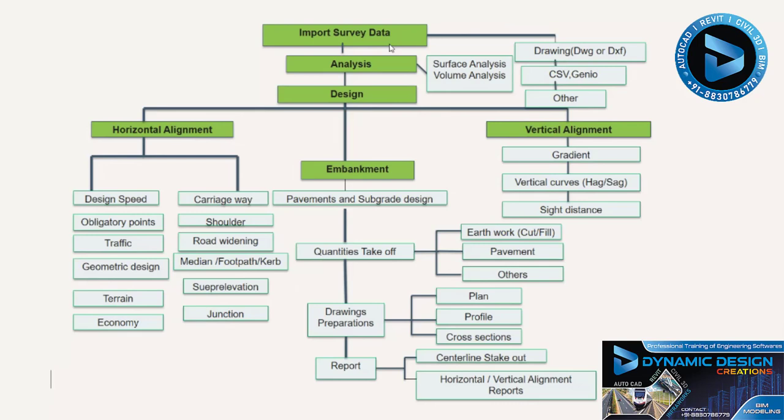In a LiDAR survey we get DEM files, DTM files and contour elevations, depending on the contour interval you record, every 10 meters, or 30 meters, or 50 centimeter intervals. They share these along with the point file, if you record point files, and the topo data.